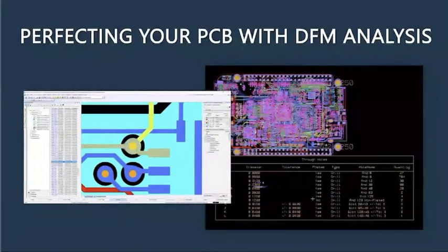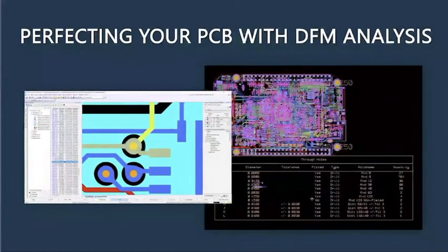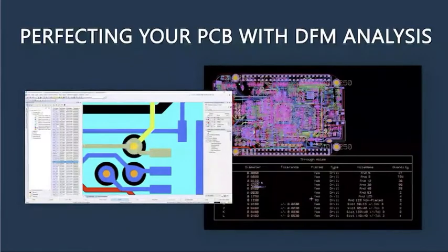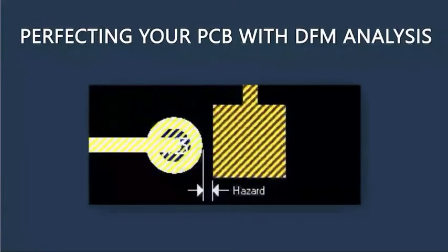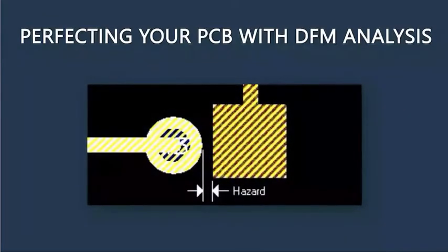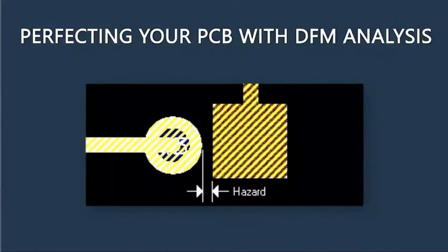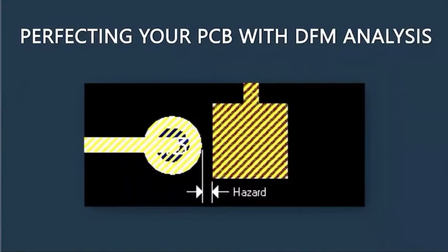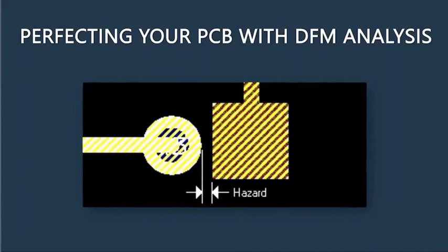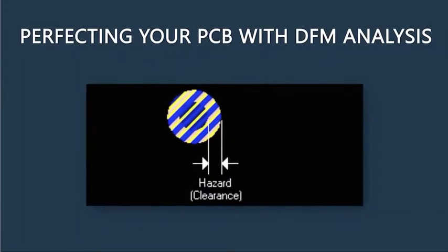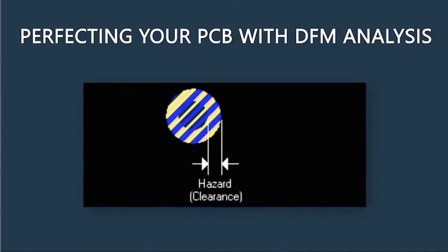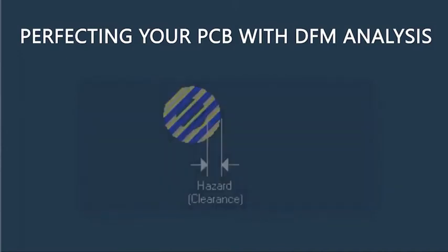There are many DFM issues to take into consideration as we design boards. A few common issues engineers tend to see are insufficient proximity, annular rings, and slivers. Proximity between traces and other electrical components can become a clear hazard. If pins miss a clearance from a plane layer, there's a chance the pin and plane can tie together all the voltage from the plane. Annular rings are the remaining ring of copper left after drilling a pad, and when designed too small can create some major issues. Pads can delaminate from the board, or disconnections can create shorts on the plane.